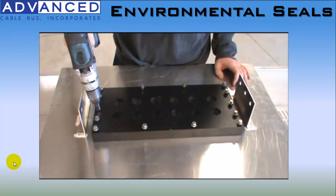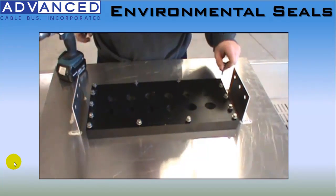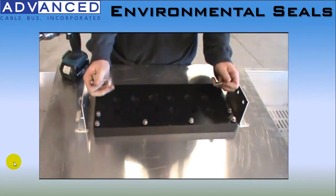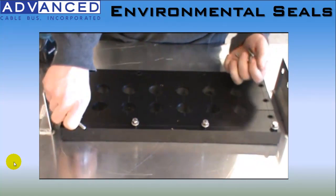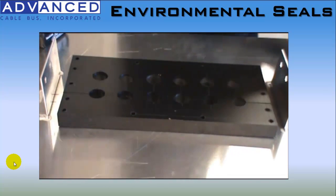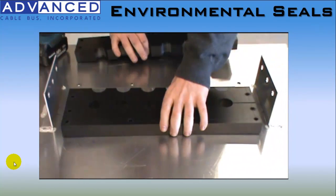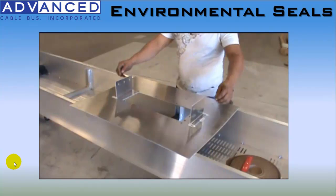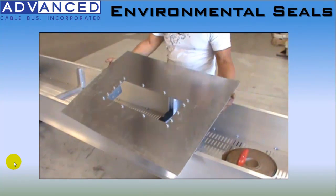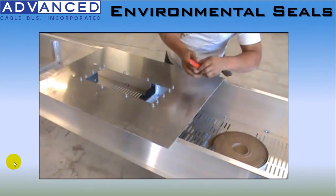The seal plate that we provide has a generic size width to it, and you can ensure that it matches your application by trimming the edges as required. The other benefit of removing the seal blocks at the beginning is so that when you place it along the wall, you would be able to mark out the wall opening and ensure that it works.